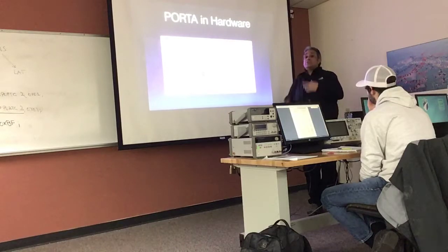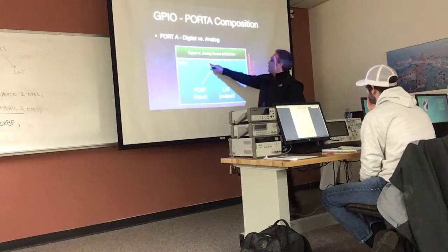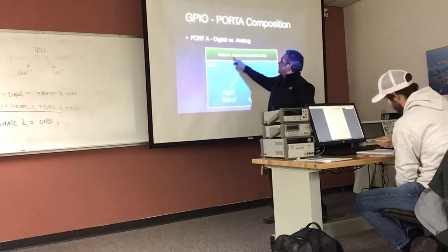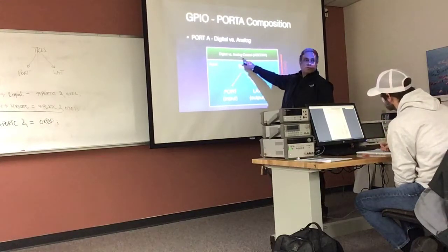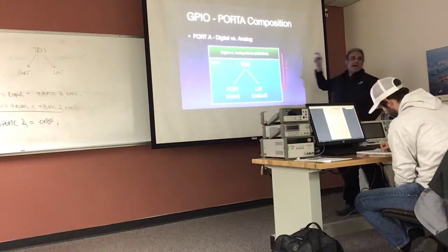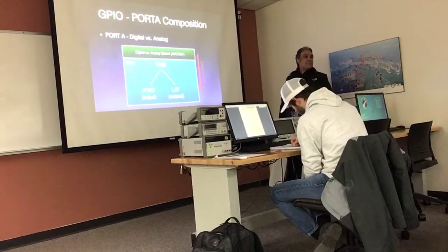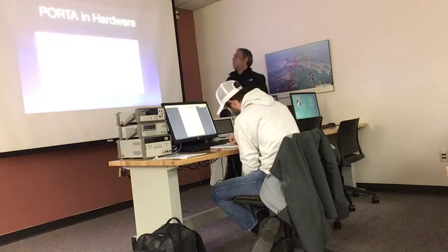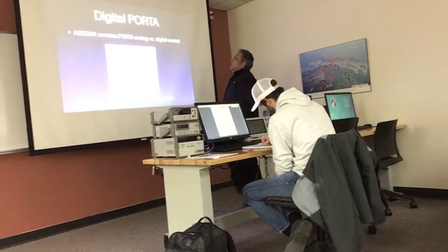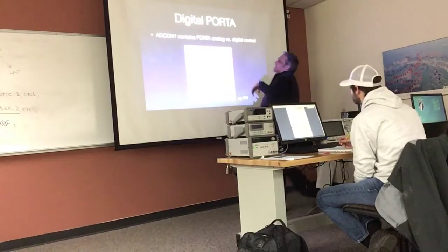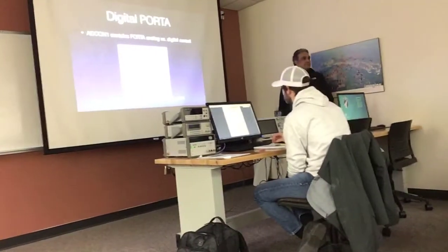So before you can use the tri-state, like we were talking about here, I have to take control of this digital versus analog behavior. See that? So on port A, this has to happen. I have to control the A to D before I can go into my digital stuff. See that? So how do we do that? The register ADCON1 exists in chapter 19.